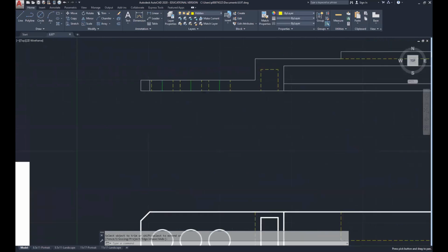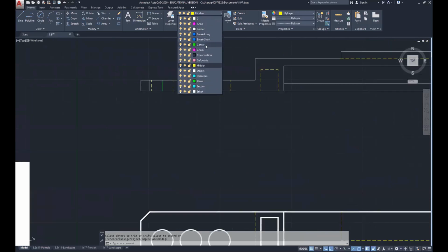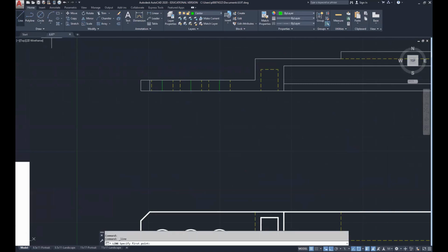So let's go ahead and fix these center lines. Now, when doing a center line, you'll notice when you draw it off to the side, it has to have a certain length before it pops, before you get that nice, clean center line. So I recommend drawing that center line off to the side until you get that nice, clean pop. Then you just place it there, right-click, enter.